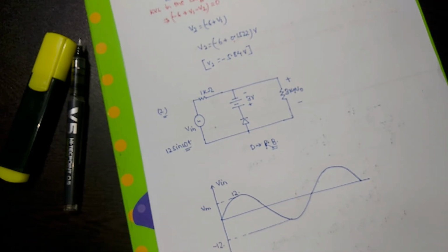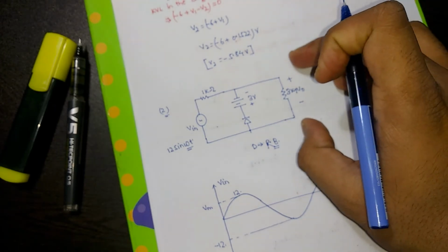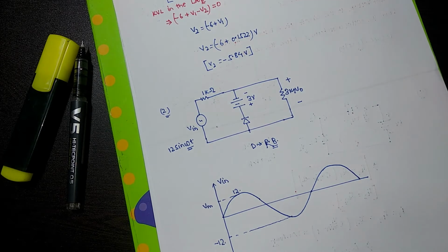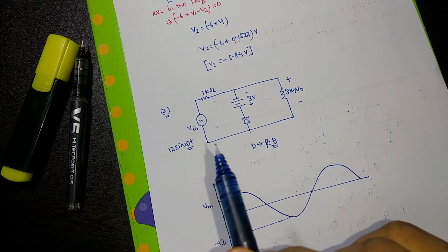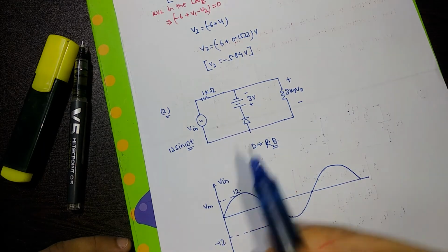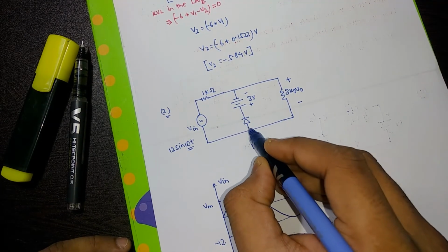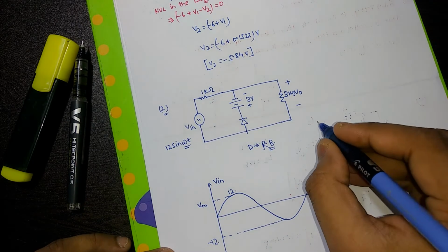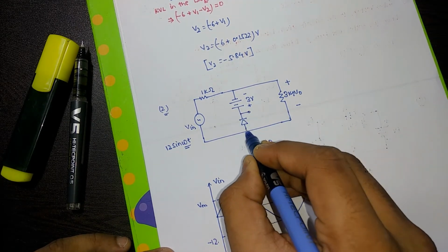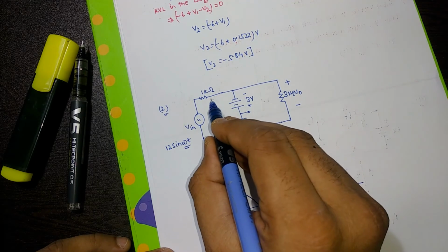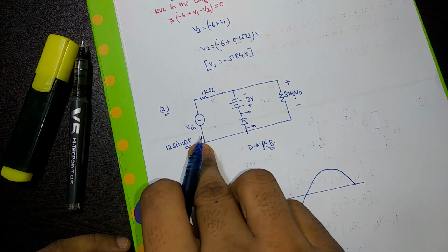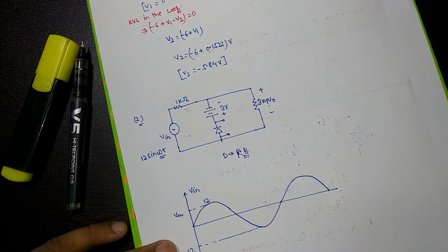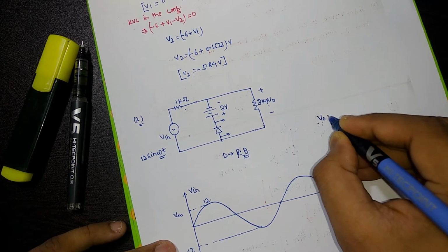Okay, now as this output terminal is regulated, I'm considering this diode to be an ideal diode because there is no internal resistance given there. So if the diode is in reverse bias, it will be open circuited, and what you will get as an output is that this will be open. Okay, so 1 kilo ohm, 3 kilo ohm, this voltage input will be divided through these 2 resistors, that is, on applying the voltage divider rule, V output will be equal to what?